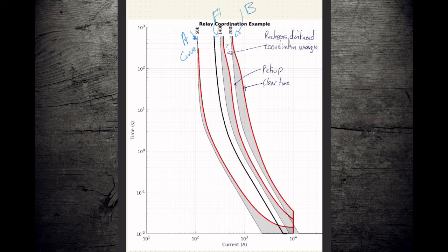And that always takes a little bit of time because the breakers have to physically swing that switch arm open, and then they're going to draw an arc internally and deal with that arc internally. So that always takes a tiny bit of time to clear. And so there's a gap between when we pick up and when we finish opening.